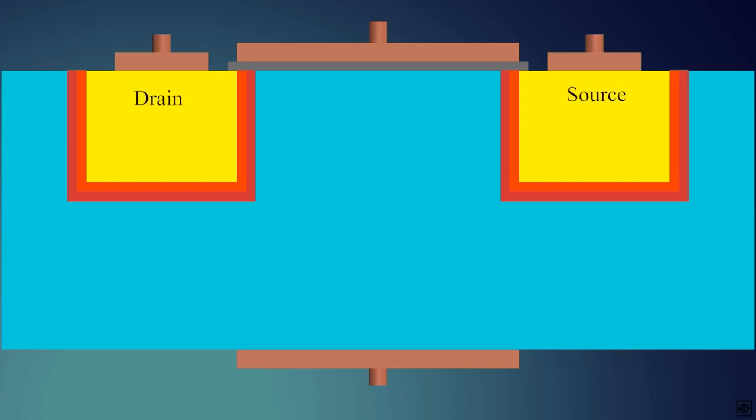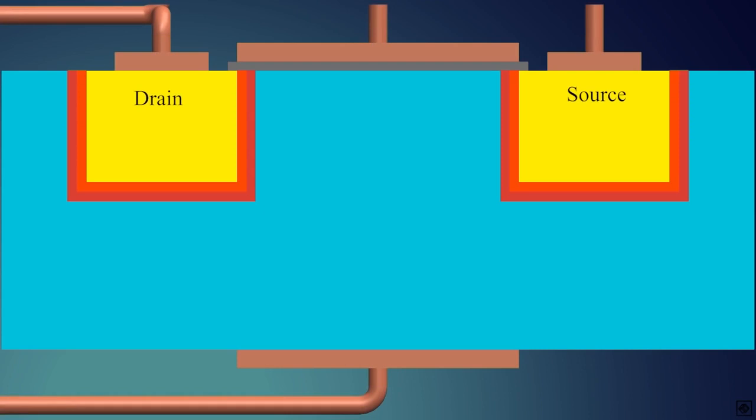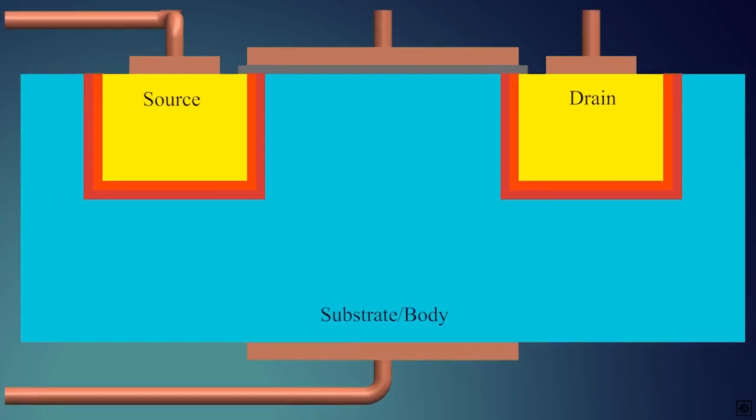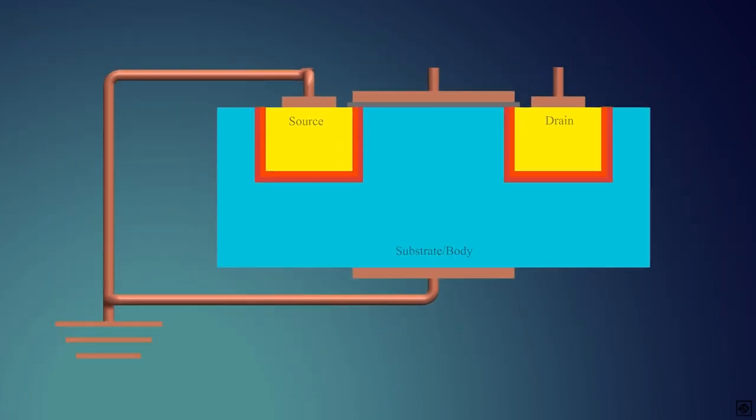As the MOSFET is symmetrical, that is, the source or the drain can be interchanged, hence, the source terminal and substrate terminal are connected internally, and the MOSFET we see has three terminals. Also, this stops any current flow from the substrate to the source as they are at the same potential.